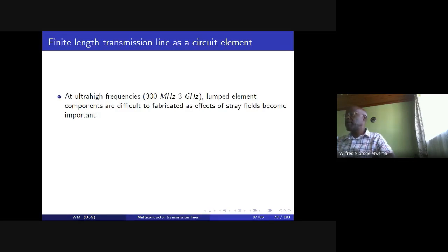So the first thing we have there is a capacitance shunting that resistor. Two, the section of line that you have, the lead, the current flowing through it will develop a magnetic field around the line, and that magnetic field per unit current is an inductance. Again, we see that the resistor now will have an inductor in series with it, and the whole mess is then shunted by a capacitor.